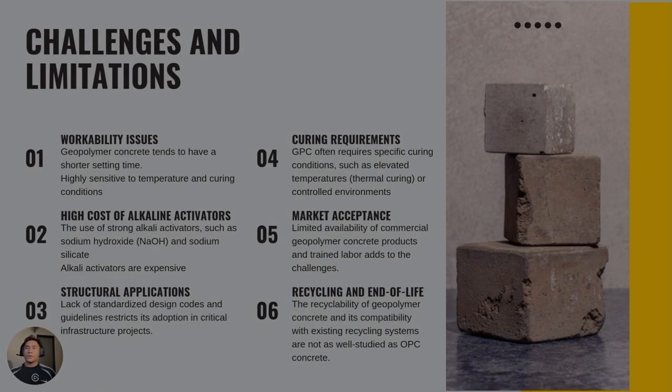Now I'm going to continue with my part, which is the challenges and limitations of geopolymer concrete. First of all, workability issues. Geopolymer concrete tends to have a shorter setting time, which can make handling and placement more challenging, especially in large-scale projects. It's also highly sensitive to temperature and curing conditions, which can complicate on-site application.